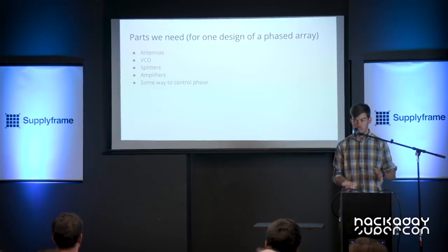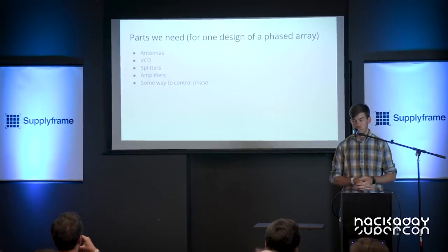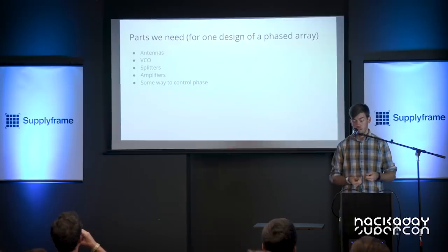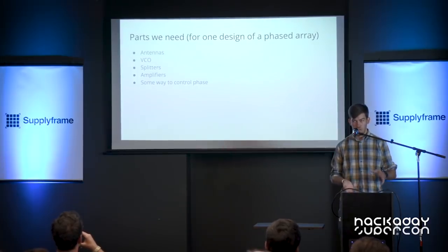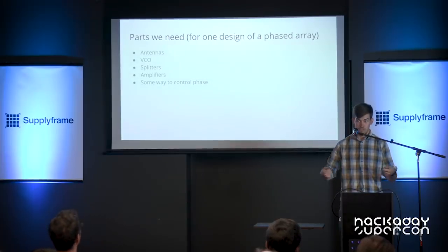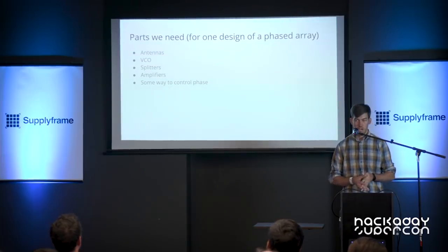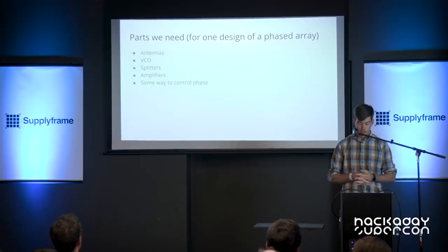If you've never done a lot of RF stuff, Mini-Circuits is a company that makes a lot of RF parts that you can't get on, like, Mouser or DigiKey. And the ones I'm calling out specifically are screw-together parts. So they are between $50 to $150 each, which can add up. But they're almost impossible to screw up because literally you just attach them together. You don't need to do any RF routing or anything like that. And you can build a 4-port array for under $1,000.